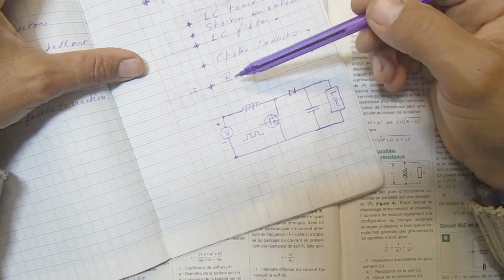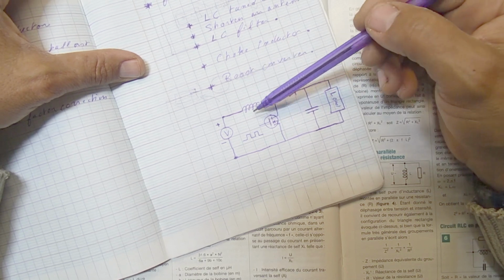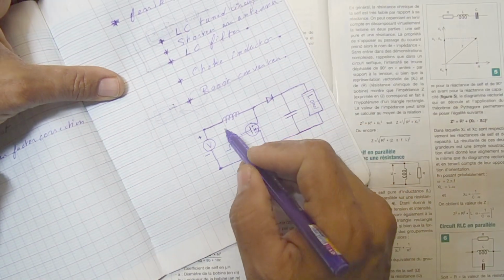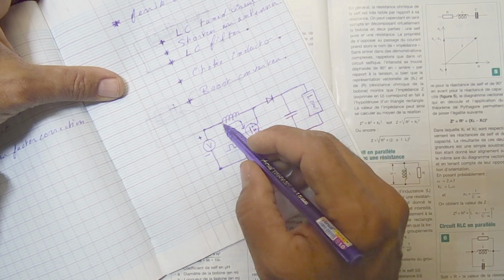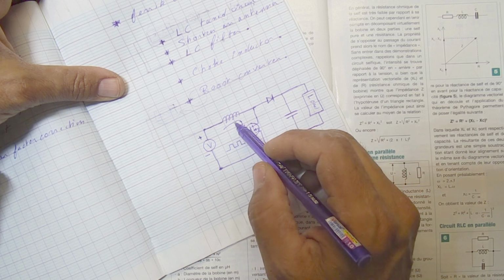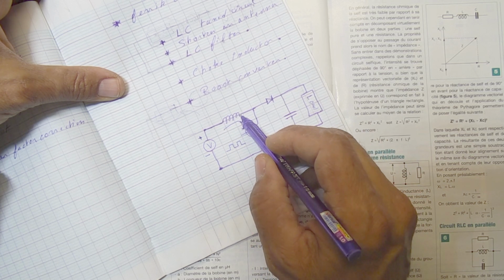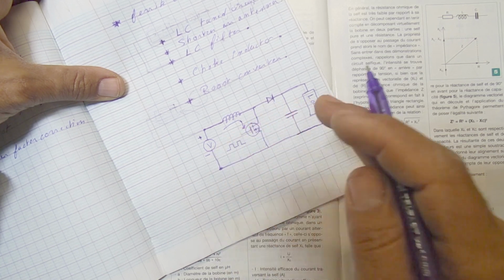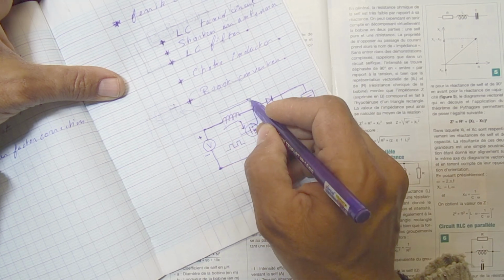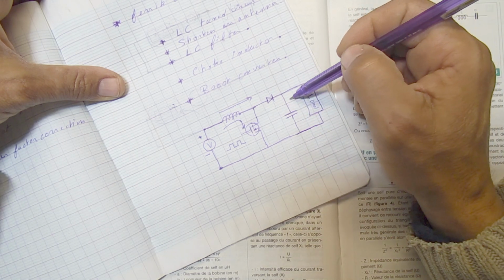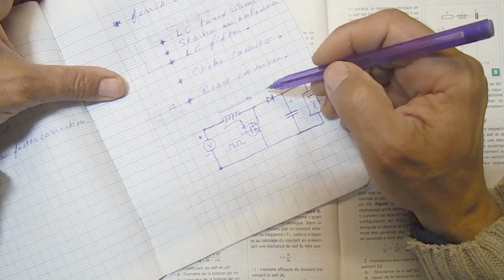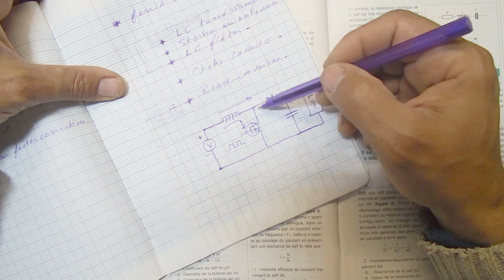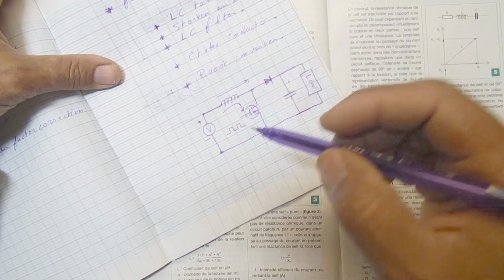Also, an inductor can be used with a DC to DC converter. For example, in this one, the boost converter. When the transistor is turned on, the current can flow in this side from the inductor to the transistor, and we energize the inductor and have some energy stored here. And when we turn the transistor off, the inductor will try to continue the current and will boost the current and charge this capacitor. This diode must be a fast diode. And the cycle repeats.